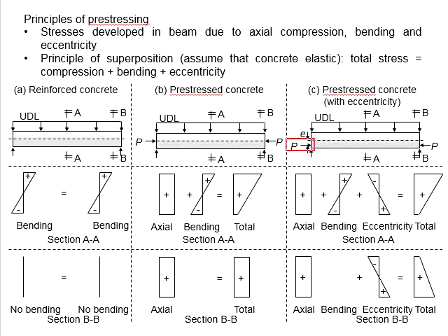Next, we look at the support regions of the pre-stressed member. There is a compressive force acting on the beam. This will give you the axial stress. The UDL does not cause any bending moment acting at the support. For that, there is no bending moment. And what you see at the support here, there is an eccentricity. Therefore, the effects of the eccentricity need to be considered.